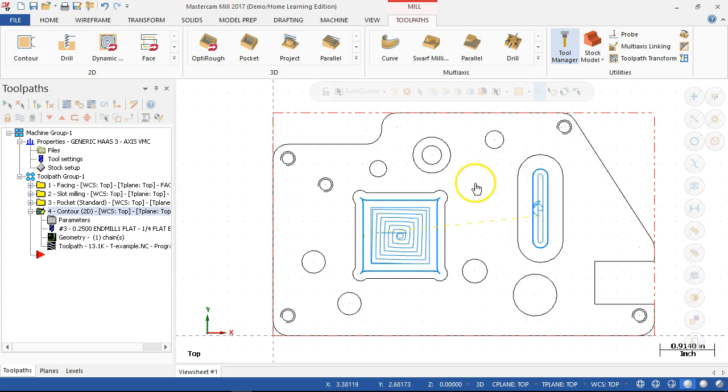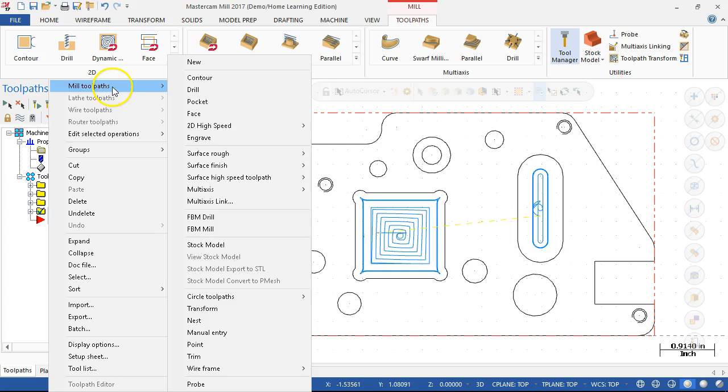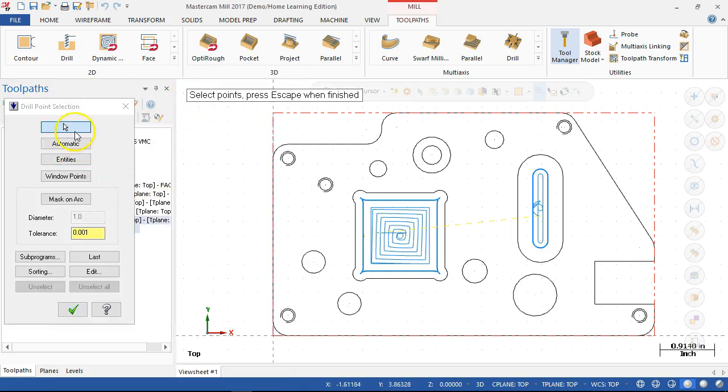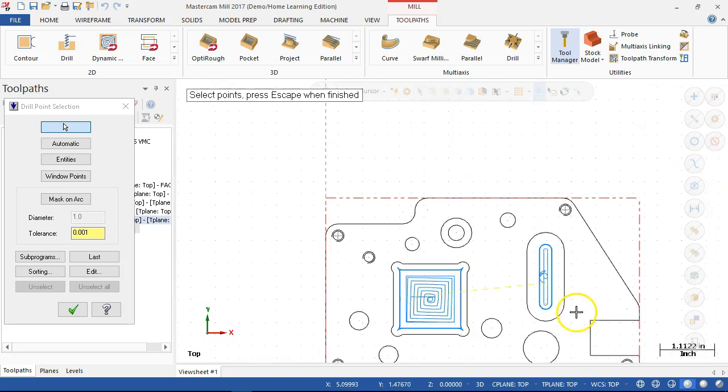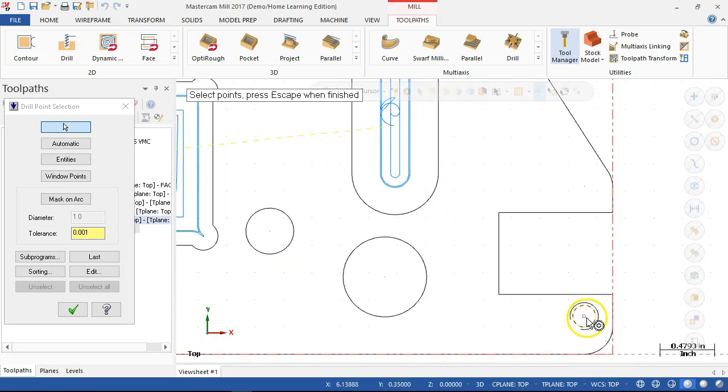So center drill and tap. Let's just go with the drill and tap. Okay, drill and tap and the drill and countersink. The other ones, we would just load up the drill and tell it to peck the holes through. And so the drill and tap, we set up for the drill and pick the points. And if we set for the mask, a lot of times it's just going to be easier to find those centers if there's not a bunch of them.